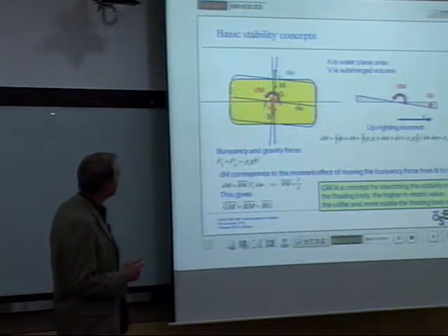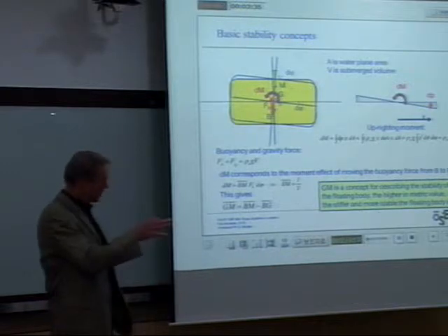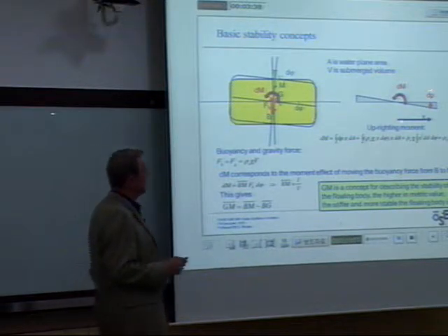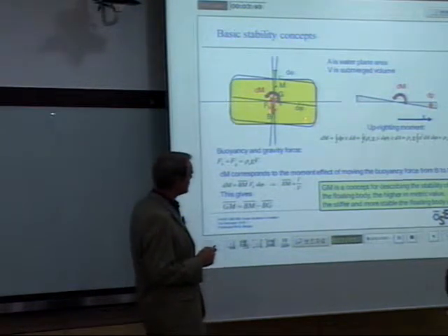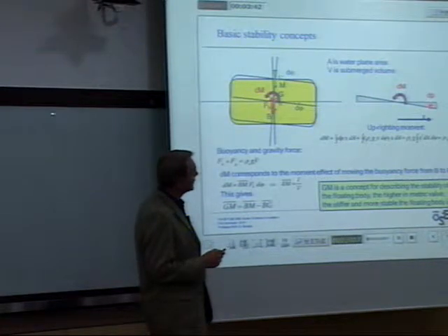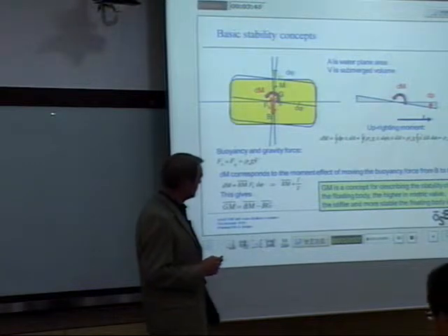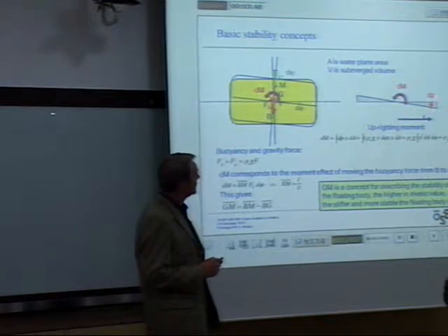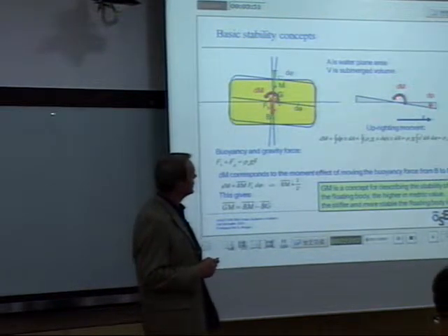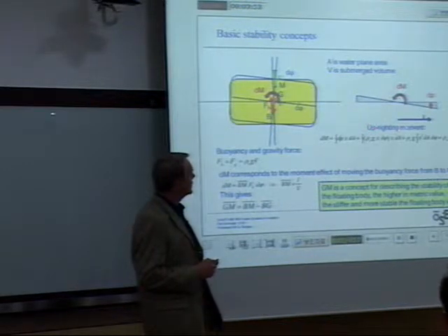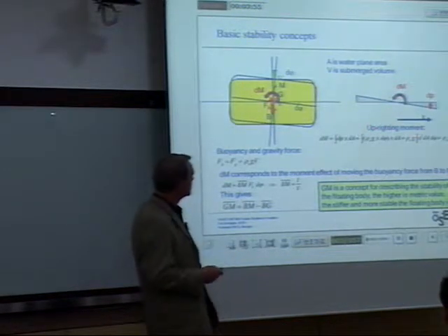And this side you lift up with the water when you rotate it. And that means a pressure difference. When this dips down, you increase the pressure on this side, right? And that gives you a contribution to what we call an uprighting moment, kind of a correction moment.